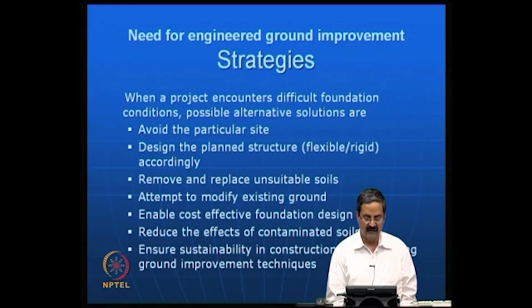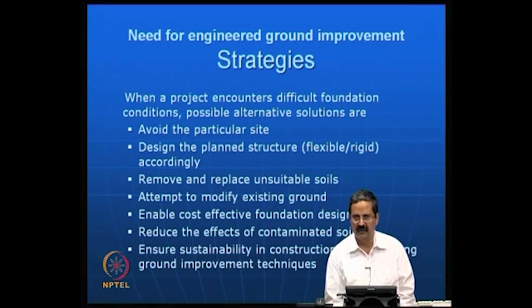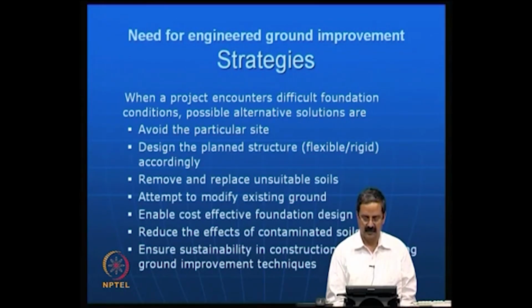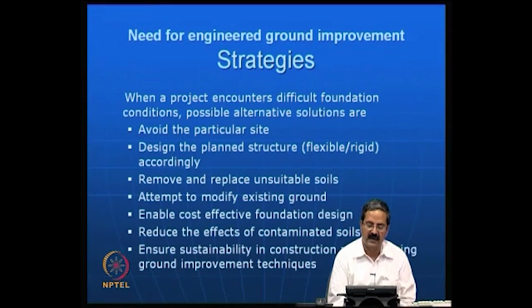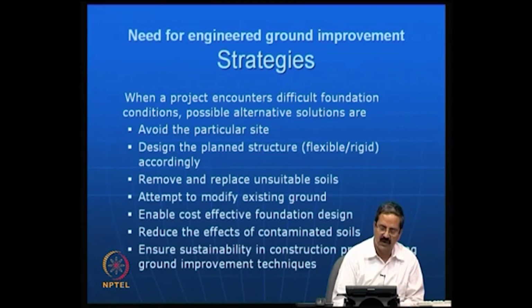Another point is the effect of contaminated soils. Nowadays, with increased demand on public infrastructure, contaminated soils exist and need to be used in a proper way. The contaminated soils should not influence our buildings. For example, any water that goes into contaminated soil should not come to your area and create problems, like for the underground water tank of your building. If it is close to a contaminated soil, there should be a proper lining system in which the contaminated soils are contained, and they do not allow the water or the seepage to come to your area. So, what we want is that contaminated soils should be properly handled, and containment of their effect is possible using ground improvement techniques.